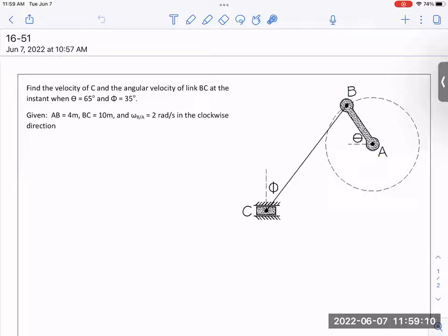And notice the driver this time is this. So this is the same exact math, but just backwards. This time I said the angular velocity of B as it rotates around A is 2 radians a second. Do you see how the crank arm is driving it this time? It's not the piston. So this is like the electric motor where B is going around that direction, and as a result, this is going to be over here going back and forth. You see that? Now I did say clockwise, so it's actually going this way, isn't it? Back and forth.